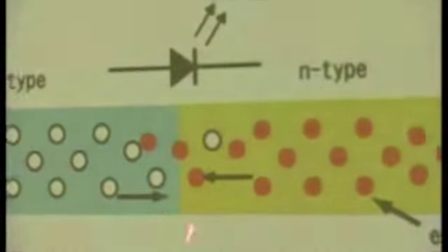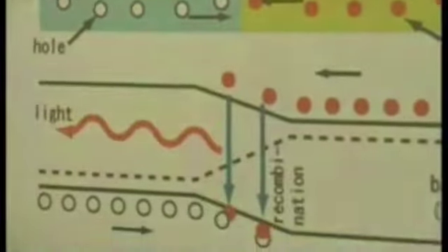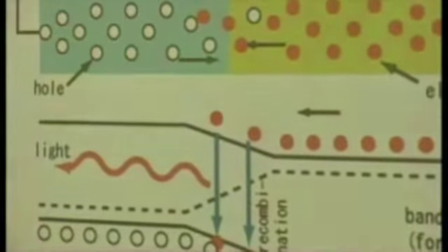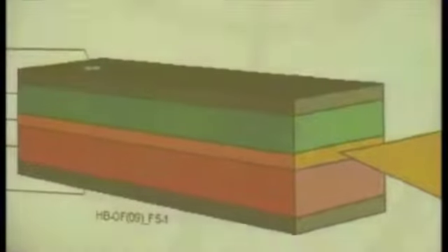This figure, you mean it? In case of avalanche diode, the slope of the PN region junction point is very steep. So we say avalanche. Avalanche means that this electron or hole goes through in an accelerated style, like an avalanche. Usually a PIN diode doesn't have so steep a slope as an avalanche diode, but avalanche diode has a very steep slope, so very effective optical to electric conversion.